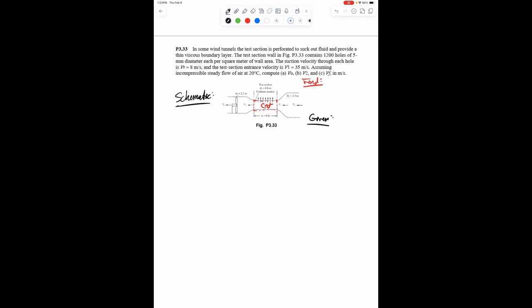So the mass conservation equation based on Reynolds transport theorem is 0 first, because the time derivative of mass per system should not be changing, should be 0, is equal to the time derivative of your control volume, rho times dV, plus the integral of your flux on your control surface, rho v vector dot normal times dA. That's equal to 0. I forgot my assumptions real quick.